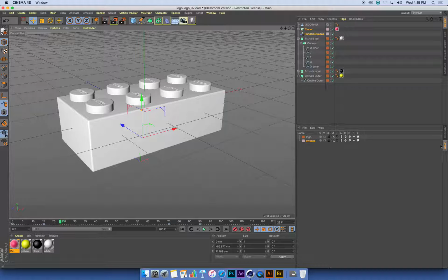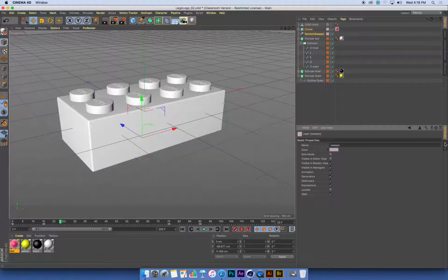The other thing I like to do with my Layers menu is I use it all the time. Anytime you start making even a small Cinema4D scene, you often end up with many objects and you want to arrange them into layers. You're often unhiding them and unlocking them, and it's a little tedious to keep having to click between these tabs on the side of the screen.